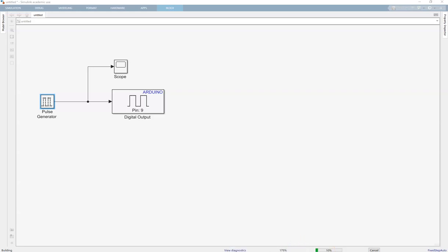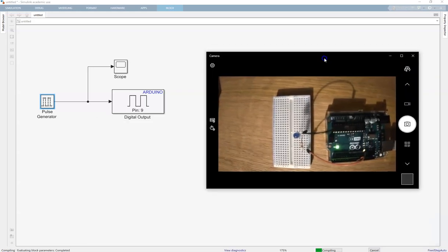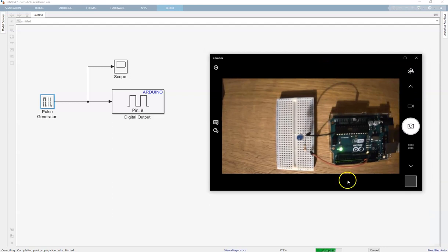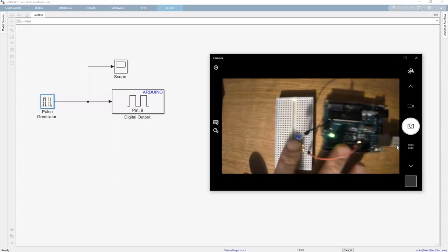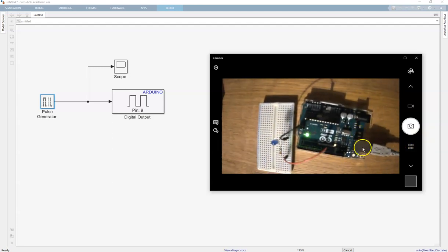And what I'm going to do is bring up this, and this is where you can see, as you remember from the notes, pin 9 here. You've got the live running through this resistor, the LED, and then here you can see it going back to the ground. And you see the USB cable here, being plugged into my computer.